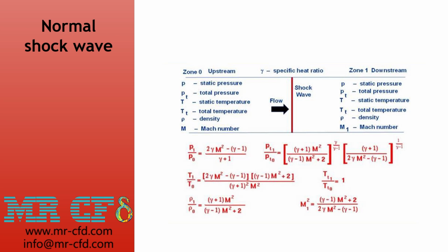So, in elementary fluid mechanics utilizing the ideal gas, a shock wave is treated discontinuously, where entropy increases abruptly as the shock passes. So the normal shock wave will be the simplest form of the shock waves, when the speed of the traveling vehicle is equal to the speed of sound.